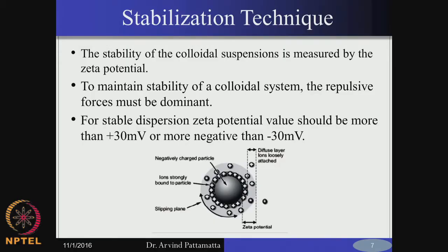So, therefore, how do you understand whether the nanofluid created is stable or not? So, one of the simplest ways is to measure the zeta potential. Since now we are talking about nanoparticle, you can imagine your electroosmosis and electrophoresis process. Okay. So, now this particular particle will have a particular charge at the surface. So, suppose if this has a positive charge, this will attract all the negative ions from the base fluid, and this will form Stern layer and diffuse layer.